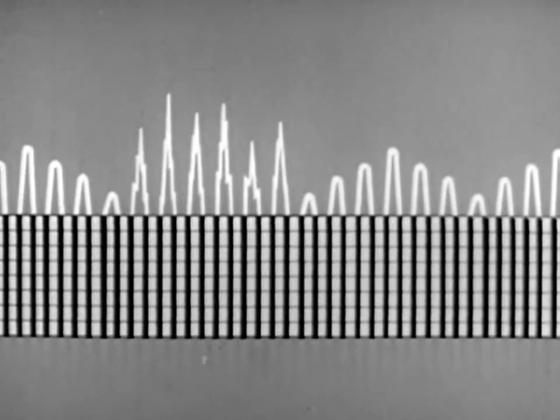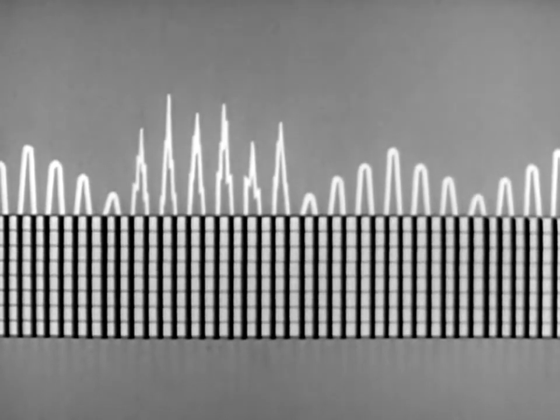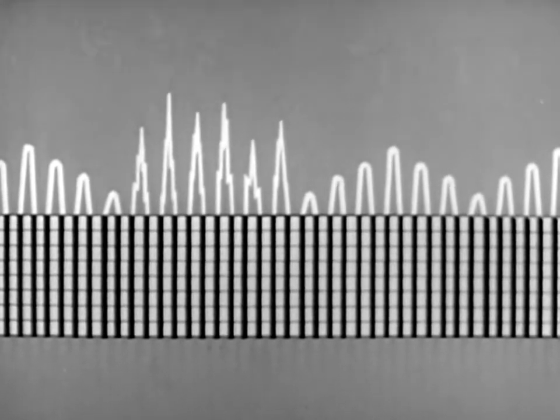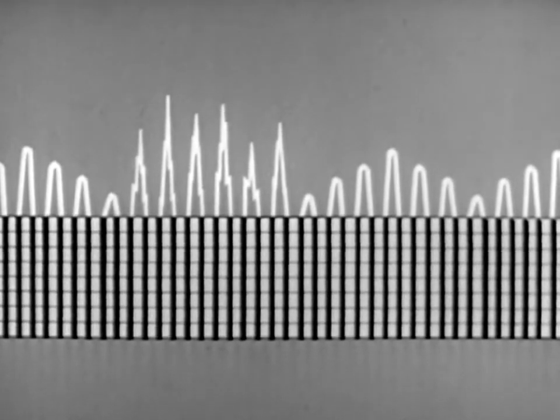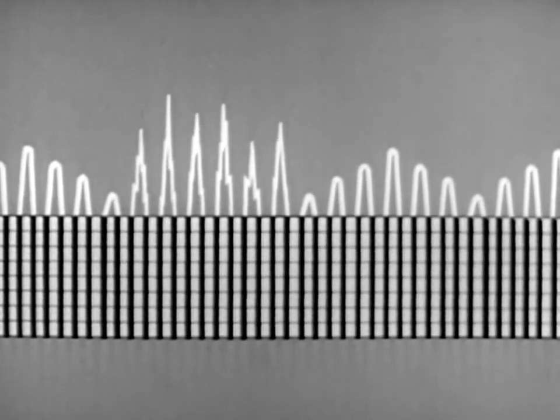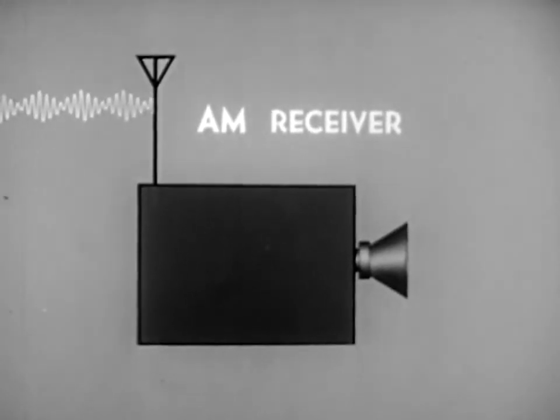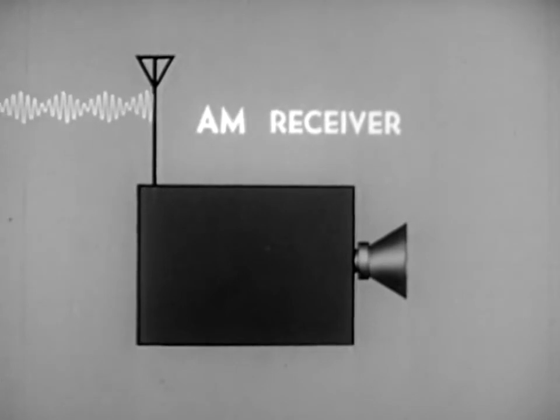The receiving antenna will pick up both the composite RF waves from the transmitting antenna and the random noises generated by the lightning. These two will combine and distort the amplitude of our desired signal, but the frequency we transmit is unaltered, unaffected by disturbances. Now, a partial review of what happens in the AM receiver. The amplitude modulated RF carrier is picked up by the receiver's antenna.